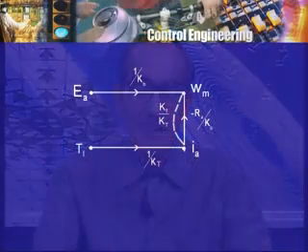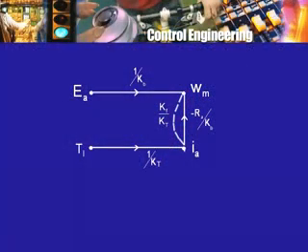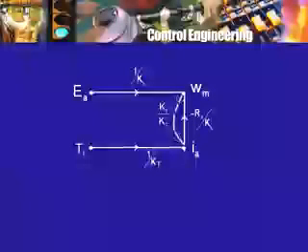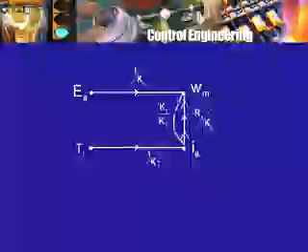The second thing that we have to find out is all the loops or closed paths in the signal flow graph. In the signal flow graph that we are looking at, either of them, the loop stands out immediately. And this is where the advantage of the signal flow graph technique is, that as a human being, if I look at a graph like this and the graph is not too complex, I can immediately spot the closed loop or the closed path. So there is this closed path which involves omega m and IA, omega m to IA through some transmittance and then back to omega m through another transmittance. So this is a loop.